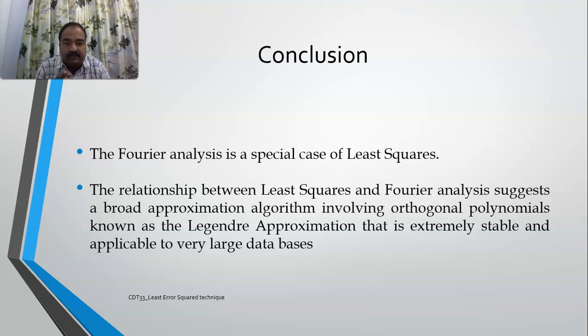From the examination point of view, I'll be giving you problems on this least error square method. But since determining a 7 by 7 matrix inverse is difficult for you, I'll be limiting myself to 3 samples. I'll be asking you to determine the DC component and also the fundamental component, which makes it 2H plus 1. DC I won't be considering, so H is 1, and 2H plus 1 is 3. So you need to do a 3 by 3 matrix in the examination.